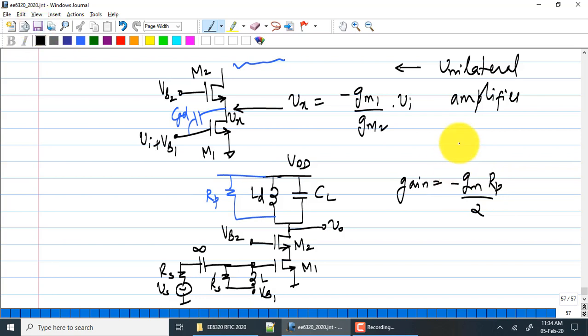Of course, please remember I am writing down the magnitude of the gain everywhere. There is a phase inversion. Okay. What is the noise figure? How do I calculate the noise figure of the circuit? Start from the fundamental definition. Total noise at the output divided by noise due to RS alone. Right? First of all, what kind of number do you folks expect?